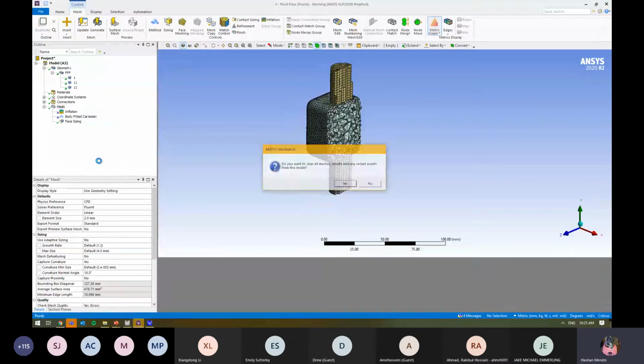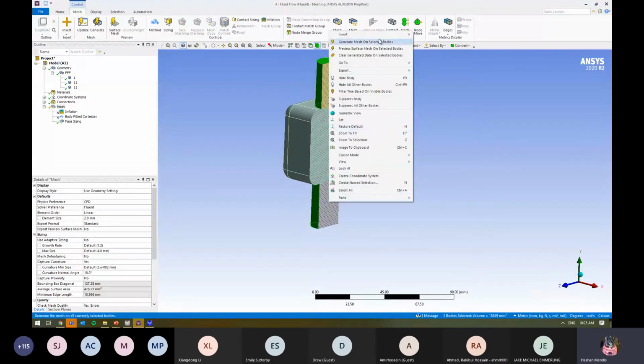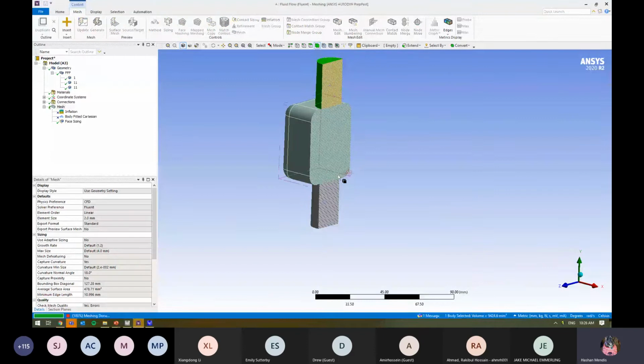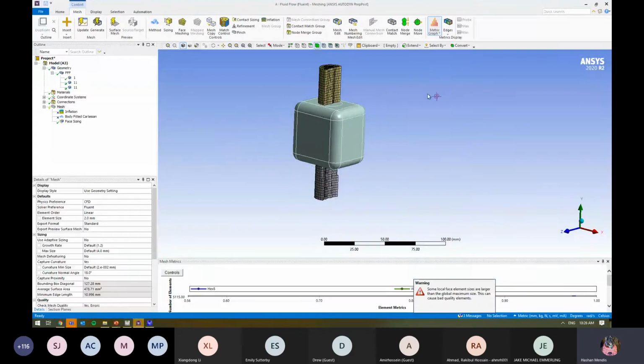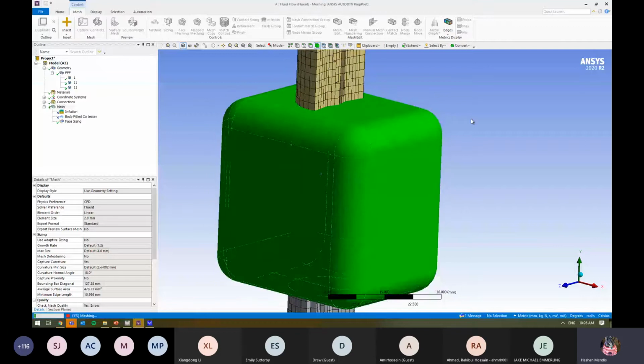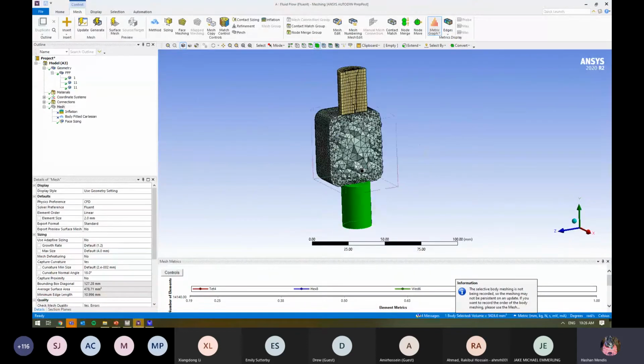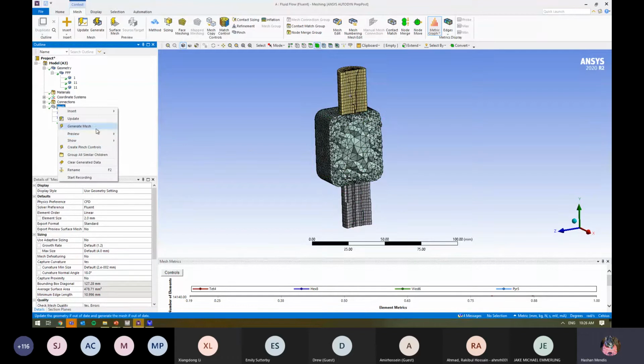The other thing, like you saw there, what you can do with these multi-body components is that you can specify meshing order as well. So you can first mesh the elements at the top if that's what you're really interested in, and then using the mesh that's generated there, you can mesh the body in the middle. Right, so maybe you're interested in what's happening specifically around these regions. You've got some very fine flow structures, and maybe you've got inflation on here, and you want to be able to just take that mesh, right?